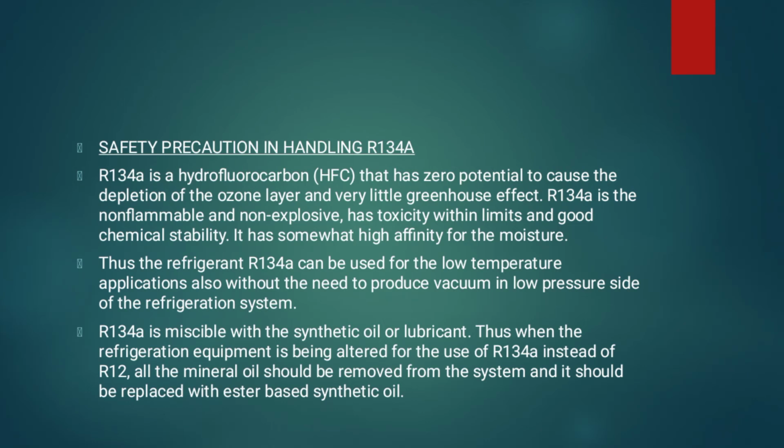So this is why R134A is recommended for substituting the R12 refrigerant. It does not cause depletion of the ozone layer and has very little greenhouse effect. We all know that the greenhouse effect can cause climate change. Alright, so R134A is non-flammable and non-explosive, has toxicity within limits, and good chemical stability.